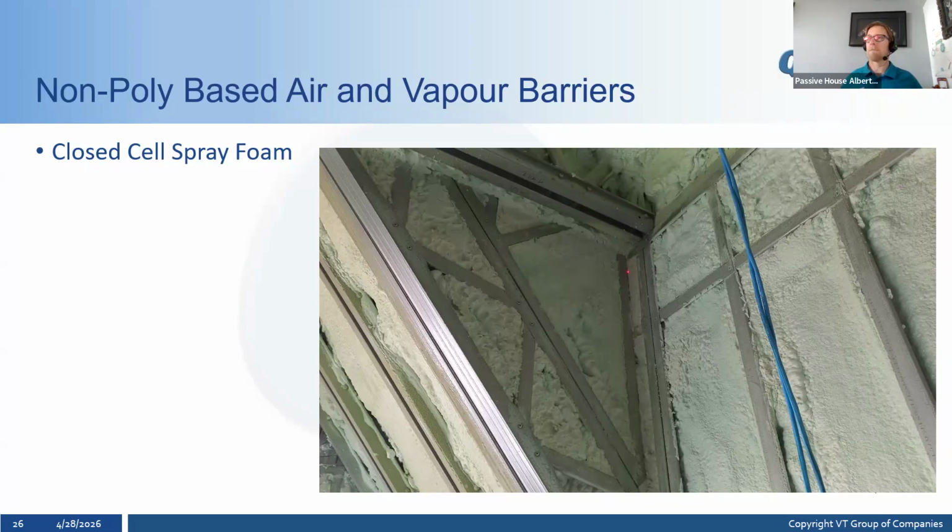Okay. Spray foam's fine if it's applied properly. Being in the diagnostics arm of construction, I've seen it go screwy. Some people will ask me when I'm doing diagnostics, would you put spray foam in your new house? No, I would not, if at all possible. Mainly that's not coming from it not performing well. I haven't seen enough data that the rigid applied spray foam remains where it's supposed to as the building shifts over the course of its life. I also haven't seen enough data, and it's the most carbon intensive insulation we have. So those are the reasons why I would be against spray foam. When it's installed properly, it appears to work fine.